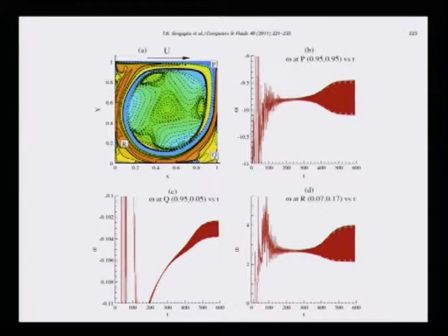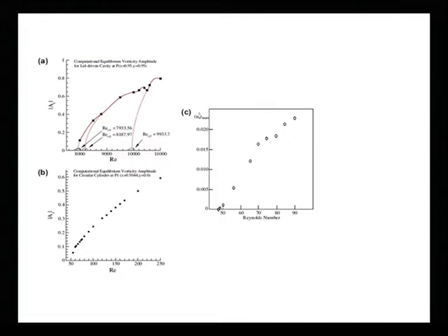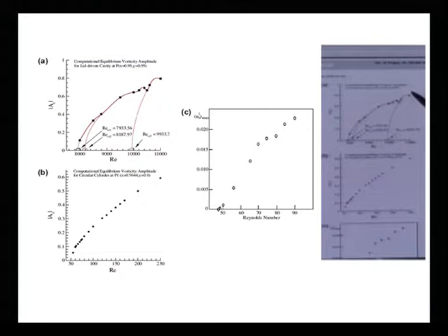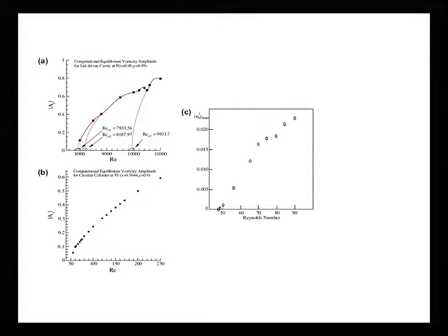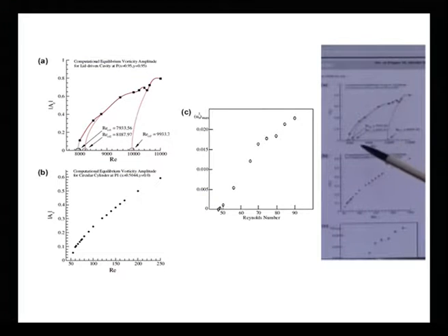So, in a sense, what we are talking about here is the same type of behavior that we saw, but now let me show you what we are going to see. If we now obtain the equilibrium amplitude and plot it as a function of Reynolds number, then what we get is the equilibrium amplitude versus Re for this lid driven cavity problem. And exactly like what we saw there, it is not a purely parabolic profile as the Landau equation would have demanded, but instead this equilibrium amplitude falls on various polynomials. In concert with what we have talked about earlier, we talk about multiple Hopf bifurcations, and different Reynolds numbers are noted here.